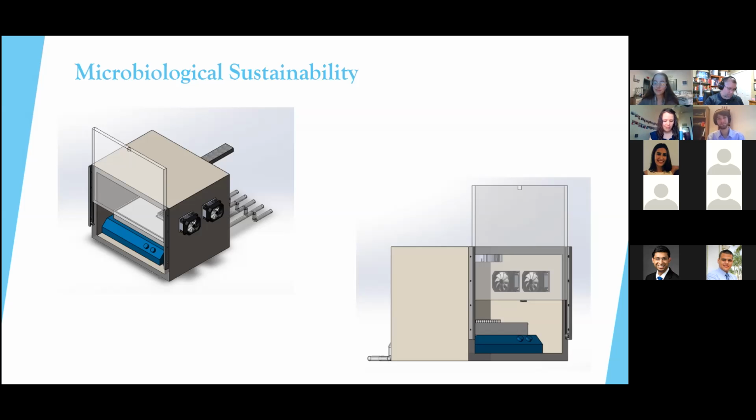Are you guys concerned at all about the 80-20 stiffness because the entire frame is made out of 80-20? When you bring it into the lab, it's going to have a tendency to move on you. Because if you remember from DML, I know Dr. Nemi's not here, he'd be loving this, but the 80-20 is great for temporary stuff, but it's very difficult to keep it rigid enough for a permanent structure because the fasteners tend to loosen over time, which you're probably going to have when you move the structure into place.